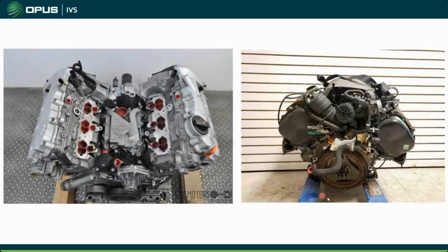So here's a real life look at this. Your air enters in through here, travels through the crankcase, comes up through the head, comes out of these 2 ports in the valve cover. We'll go back to this picture here because it's a little bit easier to see. Here's your corrugated hose coming up to your pressure regulating valve. Here's the one from the other bank. And it's a pretty simple system. At the right time and the right circumstances, it vents the system, and it works fairly well. There's not a lot going on here.